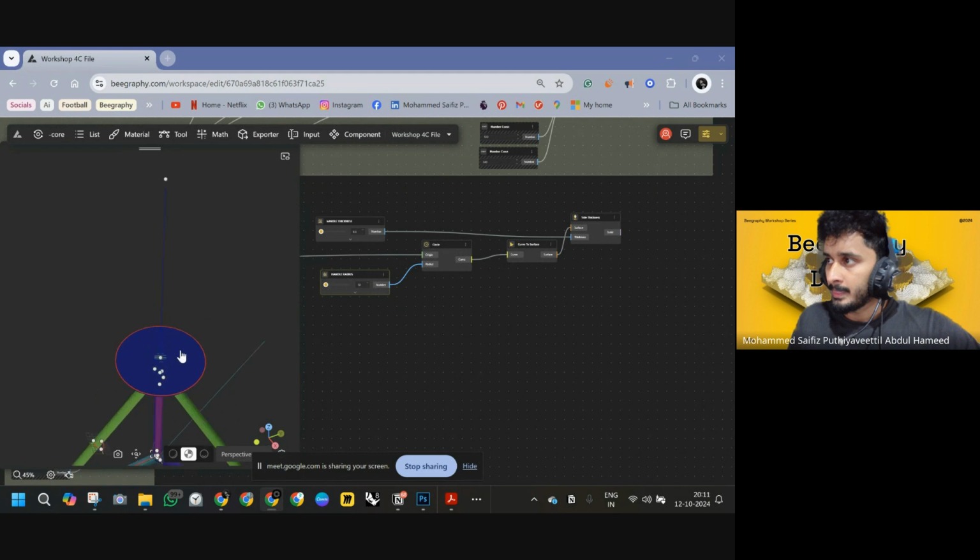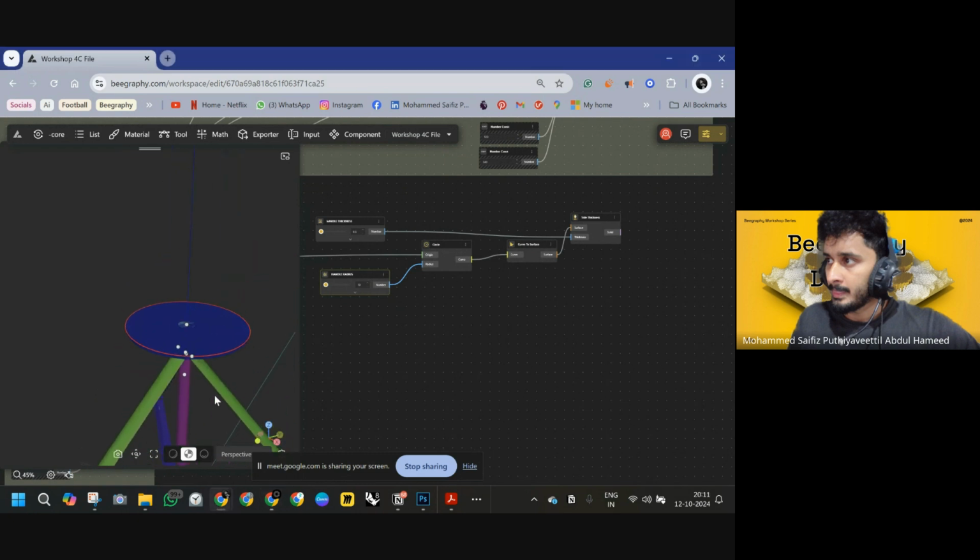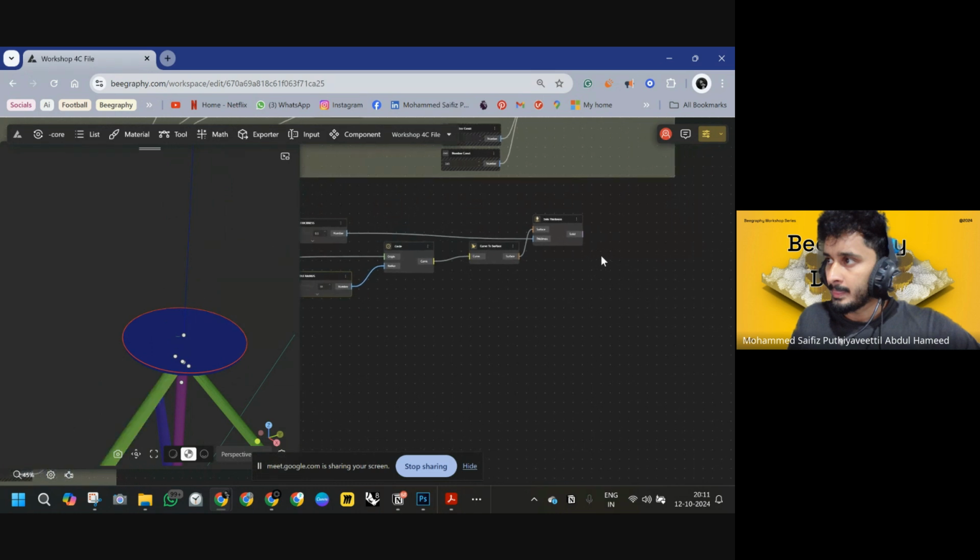Now what we'll do is we'll try to slice this into two so that we get one side of the flap, and then once we do the Boolean subtraction, and once we remove this part from it, the gap for the handle, we'll then mirror it. So first we need to split it.